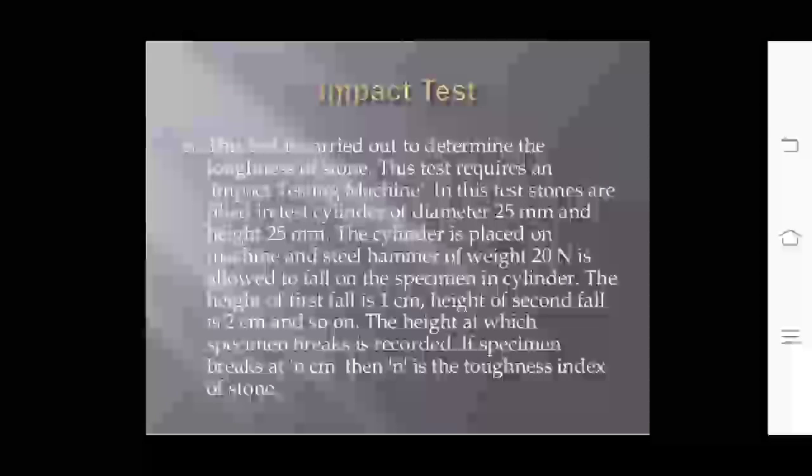The next laboratory test is impact test. This test is carried out to determine the toughness of stone. This test requires an impact testing machine. In this test, stones are filled in the test cylinder of diameter 25 mm and height of 25 mm.